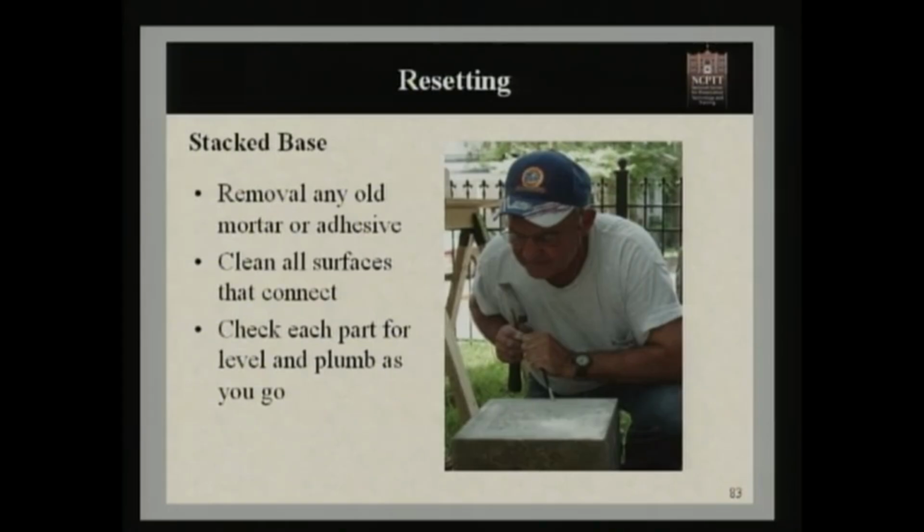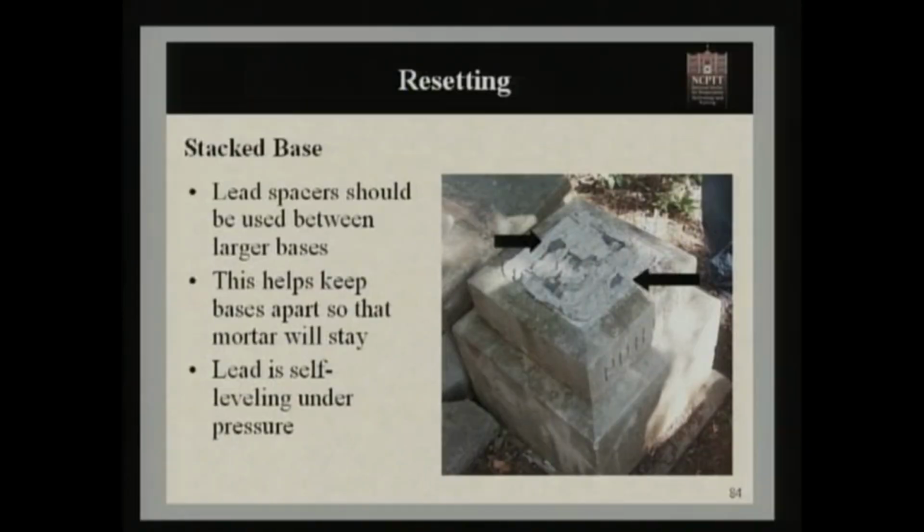When putting it back together, we want to use, again, a lime-based mortar or that grout. A lot of times lead spacers are used, and lead spacers keep the two bases apart from each other. The weight of the bases have a tendency to push down and push all your mortar out. You need that mortar in there to provide a cushion and also to keep water from getting in between these areas. So the lead spacers actually help keep it a good even space so that the mortar will stay in place.